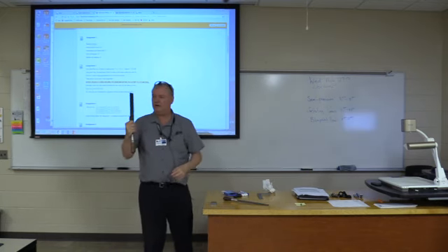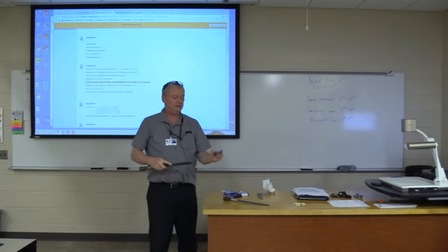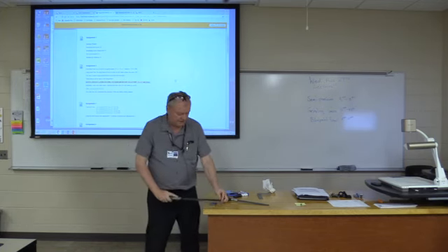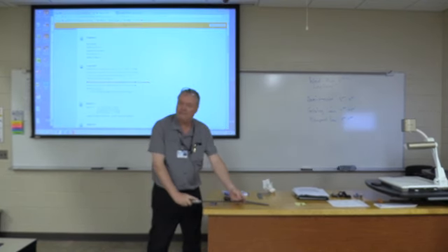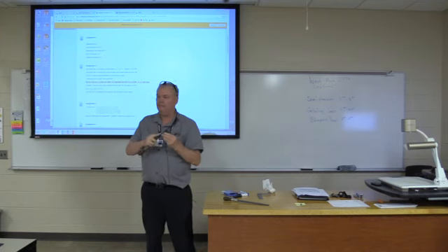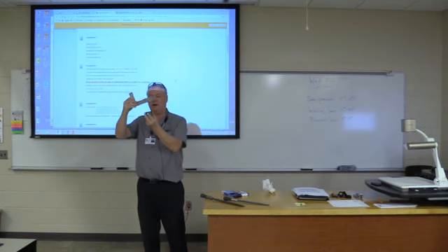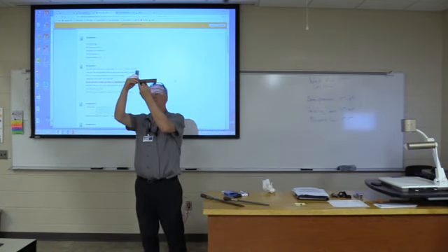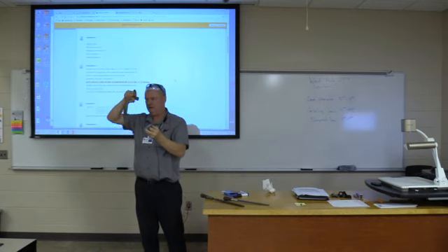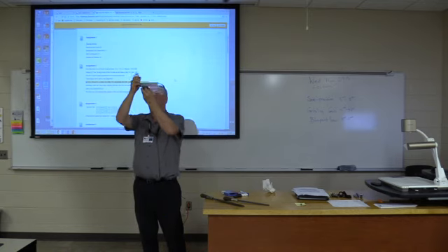So what you start off with is a rough file, and I'm going to talk a little bit about some of the hand tools we use. With this in the vise, you're going to be working this edge and filing it flat. We want this face to be flat so that when I take the machinist square and hold it up to the light, I don't want to see any sort of bend, curve going inward or upward. I don't want to see it rocking. It needs to be flat within 5/1000ths.